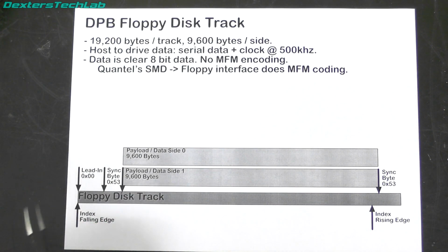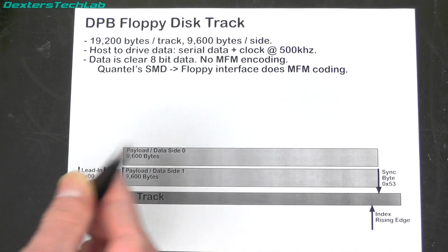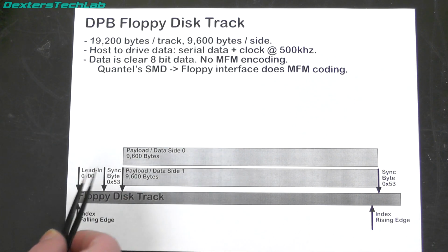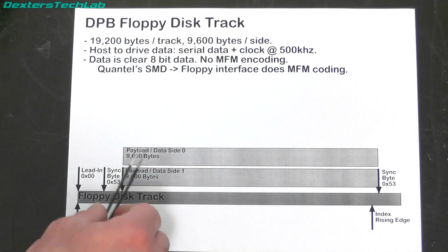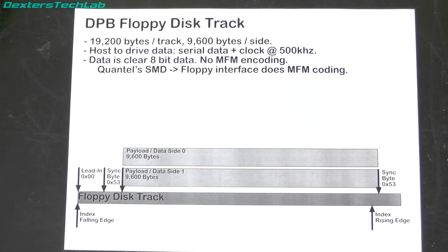Now, as I said before, that either goes to the disk buffer, the RAM that's on the disk buffer card, or it gets injected directly into the system bus and into one of the stores in the DPB. And because we have two sides, there is a point where the machine switches over and reads the second side to get the full track of data that is available.